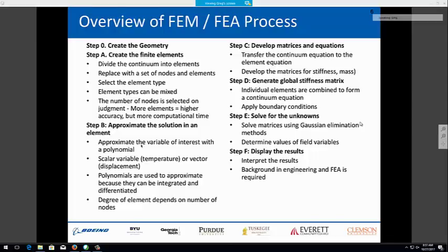There are some advanced types of analysis that can be performed. There is a combined CFD and static structural analysis, okay? But here are some examples of analyses that you can do. And essentially what Workbench allows us to do is to drag these analyses over onto this palette, okay? So just to show you a real quick example, I want to do a static structural. I'm going to drag this static structural.